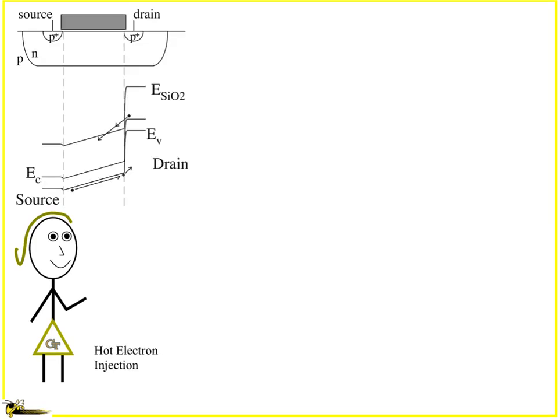This will be fun. And so what you end up getting is you can look at the band diagrams, and this is talking about what the band diagram would look like at a cryo temperature. And the cool part here is that your depletion regions are almost negligible, which makes all of your efficiencies for tunneling, for all of the hot carrier effects, quite good and relatively ballistic in these structures. And there's a lot to really get into that.